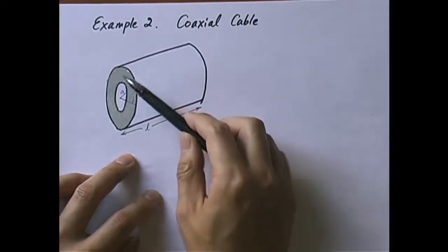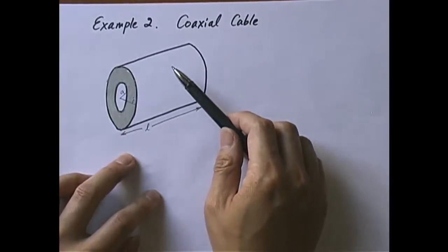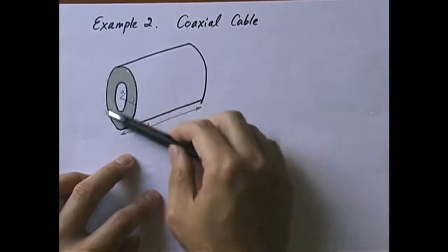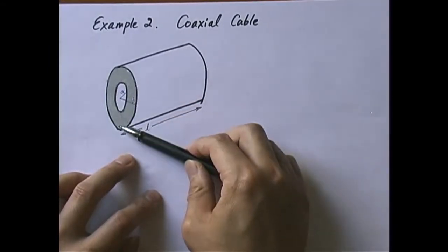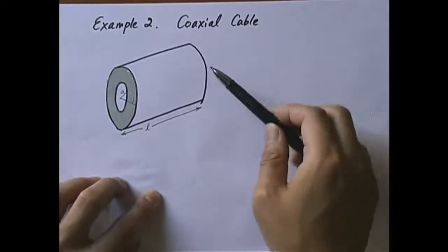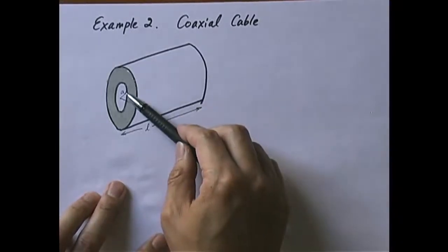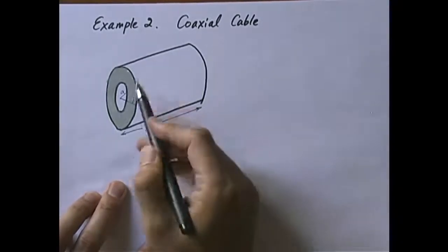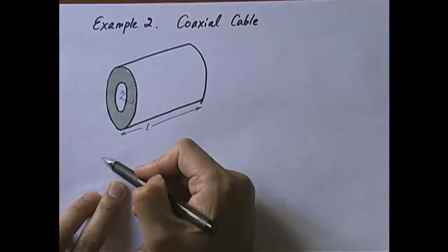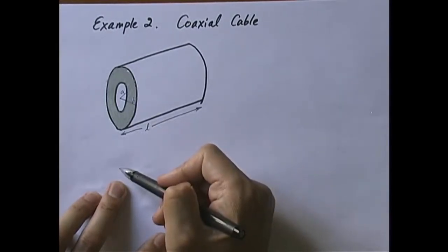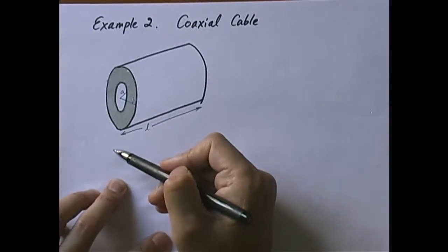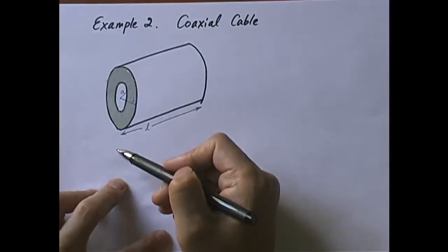That is very different. To do the first, you need to hook up a battery between this circular region and that circular region. So you connect it like this. But to let the current flow from the inner surface to the outer surface, you need to hook up the inner cylindrical surface to a certain voltage and the outer cylindrical surface to another voltage. In other words, you connect the battery like this and like that. You will create very different current flows, and therefore the resistance will also be very different.